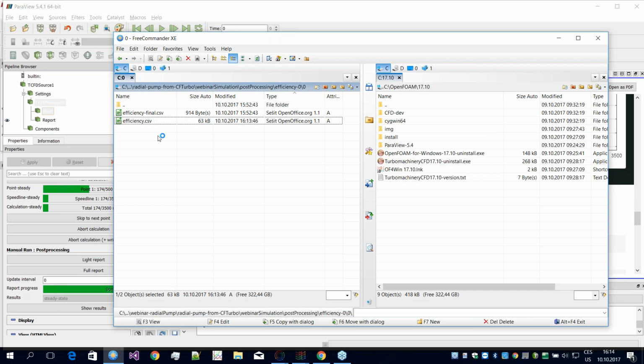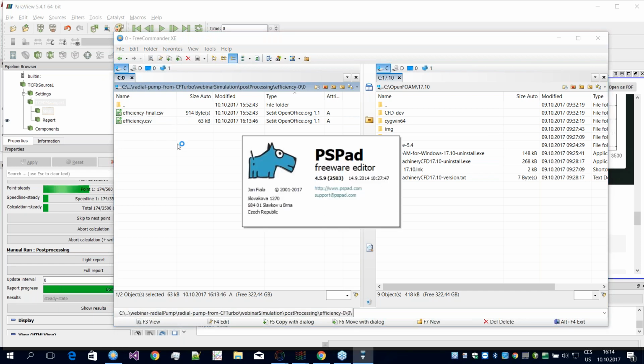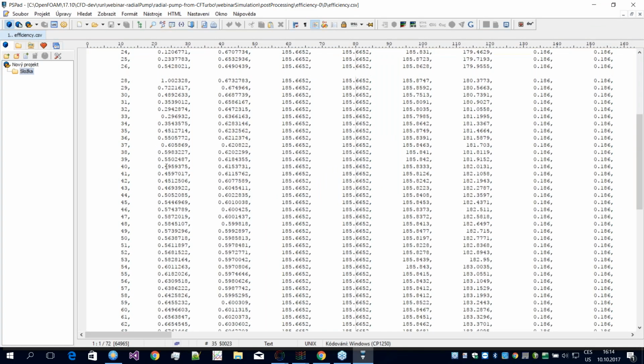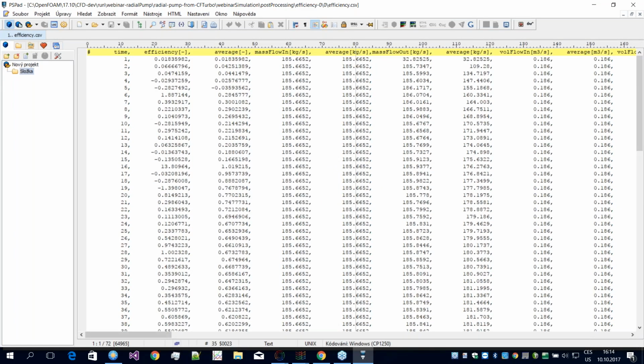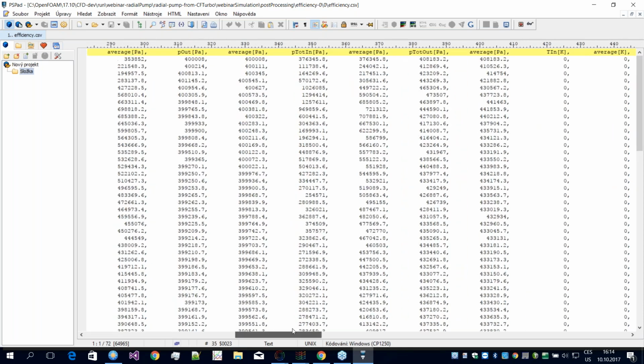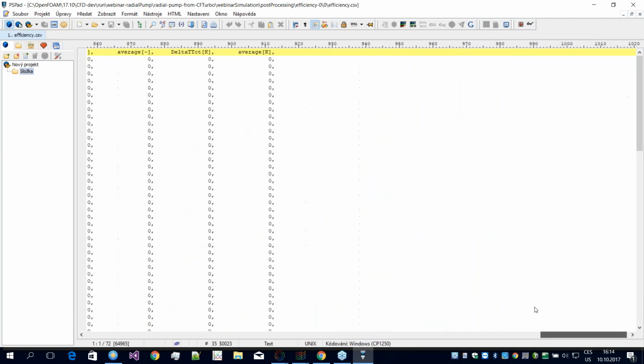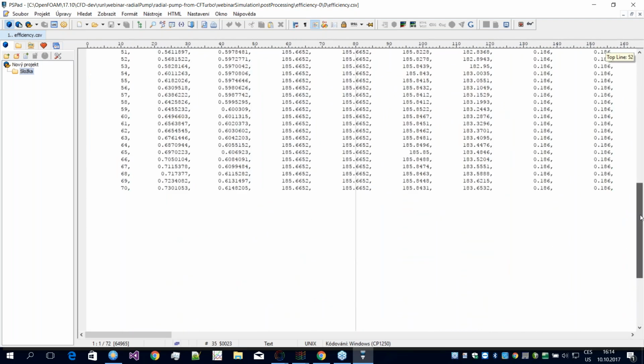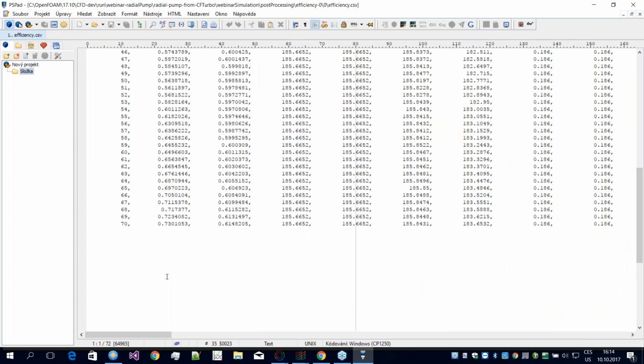Oh yeah, something is happening. So here you have all values for all iterations. For example, in each iteration you can follow the efficiency, average efficiency, the top pressure at the inlet. So every value can be followed runtime, both within the graphical user interface or directly in the given file in the case. Okay, thank you, Radek.